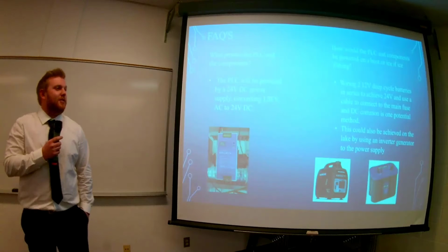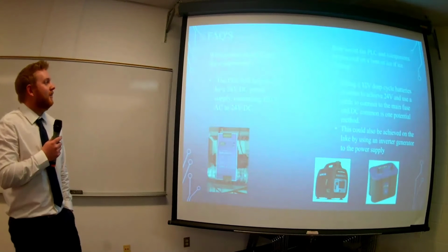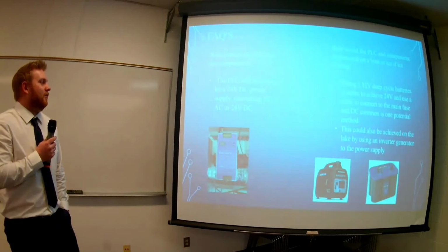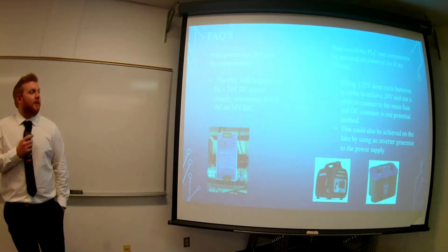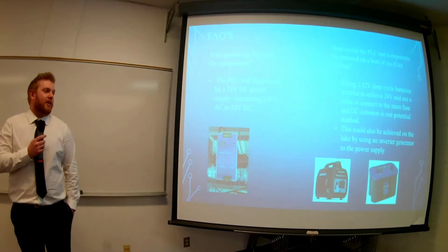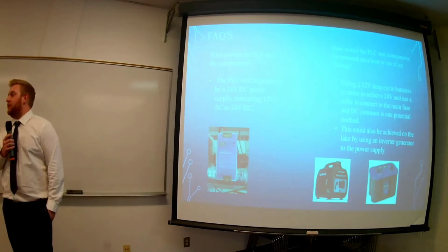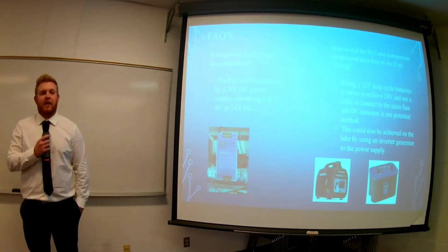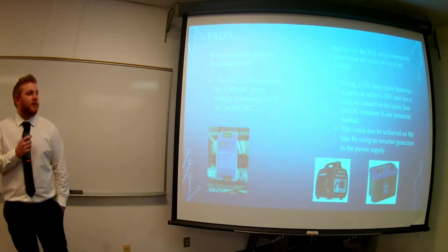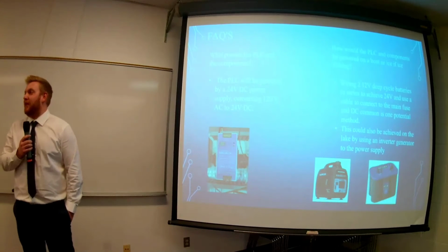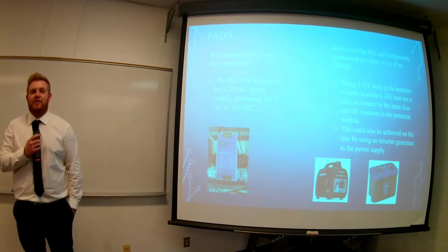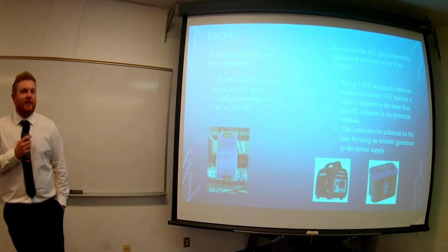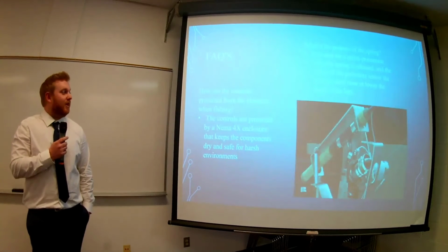And then some questions that we were asked along the way. What powers the PLC? We use a 24 DC power supply that converts 120 into 24. How would this be done in the real world, fishing? You could either use two 24-volt deep cell batteries run in series and connect that directly to the 24 main fuse. However, we could not afford those batteries, so we just use 120 power. Or you could use a generator, but no one likes to listen to a generator when they're fishing, so the battery option is definitely the best.